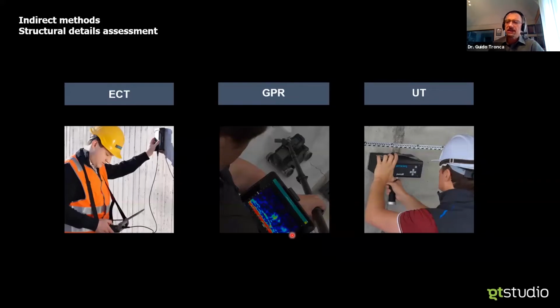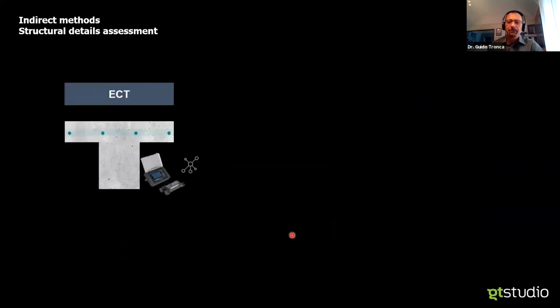All these techniques provide an image, a visual insight of what's inside an object. And let's start with a general overview of all three of them. Rebar location, we'll see, it's the gold standard for steel rebars, the one typically accepted for measuring accurately cover, estimating diameters.